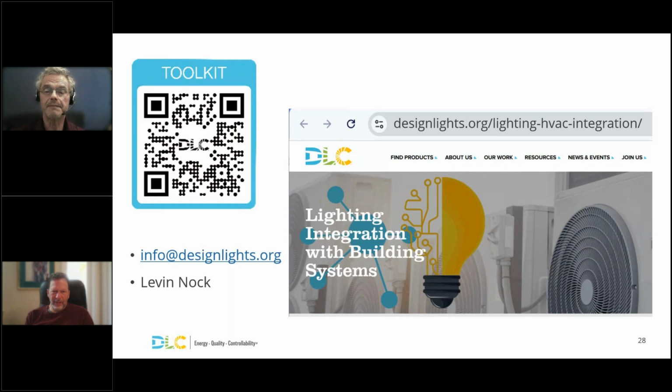Okay. Yes. So the best practice for getting the most granular data and the most energy savings is to use luminaire level lighting controls that have an occupancy sensor on every luminaire.